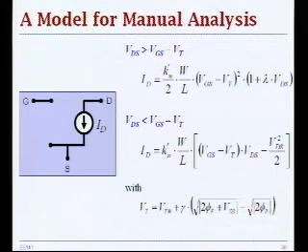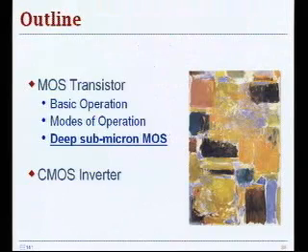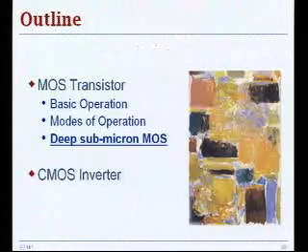You need this threshold, you need this gamma, the lambda parameter, and you need the transconductance parameter, which is a property of your oxide and your gate material. In discussions and homeworks, you will have the opportunity to play with these parameters and understand better where they come from. So now if you know all of this, that's good, but forget it.